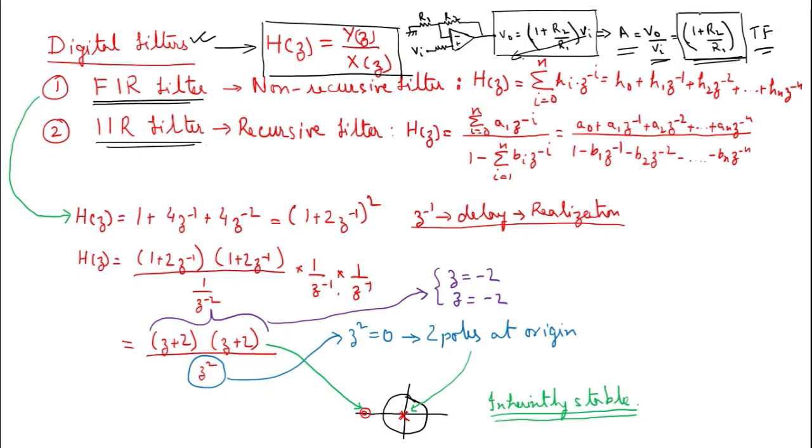Now, since in this transfer function we have R1 and R2, this transfer function is basically a frequency independent transfer function, and hence it is usually represented with A. However, instead of this, if we include some reactance components, say Xc or Xl, or a combination of both of these, then this gain would become dependent on the frequency of the input voltage, right?